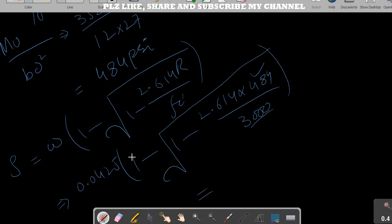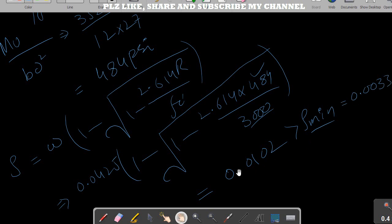So if we use the calculator, we got the value from this, 0.0102, which is greater than rho minimum. We have already calculated rho minimum in part 1A. This is 0.0033. In part 1A we calculated this one, right? So this is my rho value.